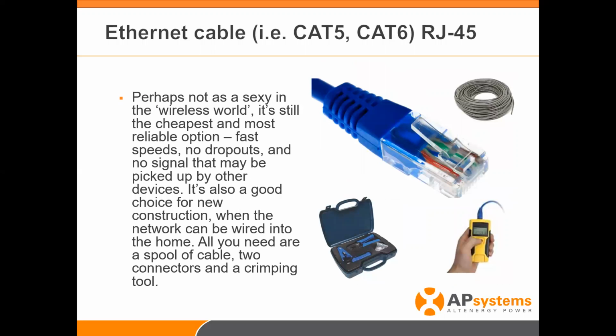So one thing I always recommend, and if you come to any of these classes, I always recommend an Ethernet cable connection. APsystems has made it super easy for you to do this, because with the advent of the ECU-R, you're able to take that gateway and put it right in the customer's office, plugged in directly via Ethernet cable to their router. What we find is if, let's say, for example, customers are using AT&T service today and they switch over to Comcast, if there's 4 things plugged into the back of the router, likelihood is they're going to put 4 things back into the new router.